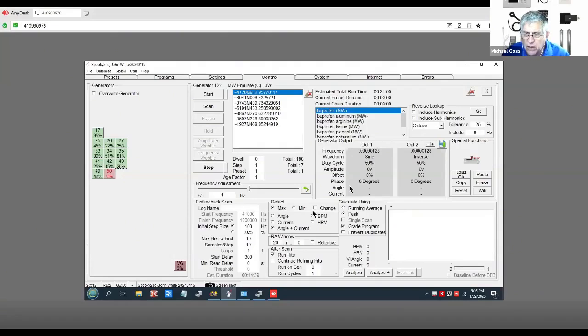Jeremy Schneider: Is there a limit to length of BNC cable when using contact? Not in my opinion. I have a 20-foot one as an extension, so no, there shouldn't be a limit. You should use a 50 ohm cable, but you can get whatever you want. I wouldn't go crazy with it, but you can definitely use a 50 ohm cable and do a 15-foot or whatever, a 6-foot, whatever you need from that point of view. But don't use 50 or 100.